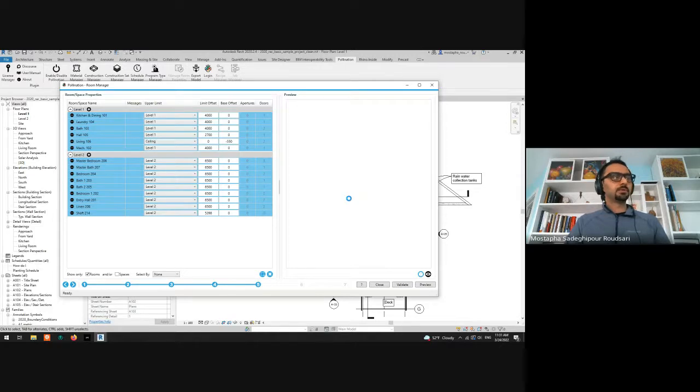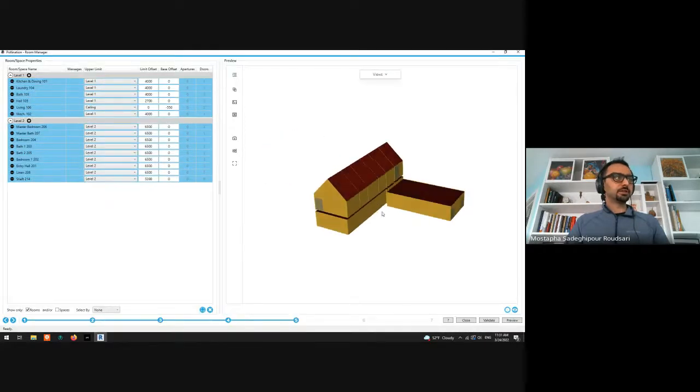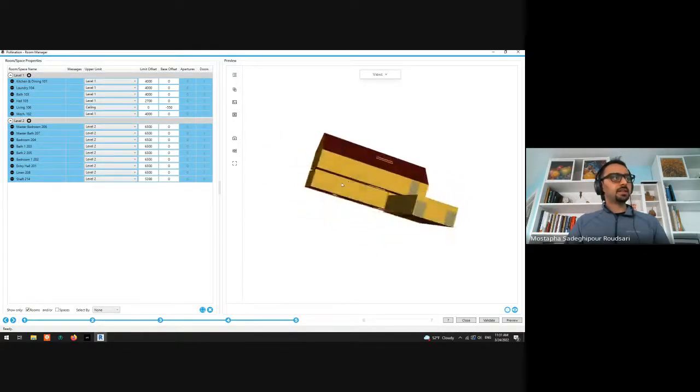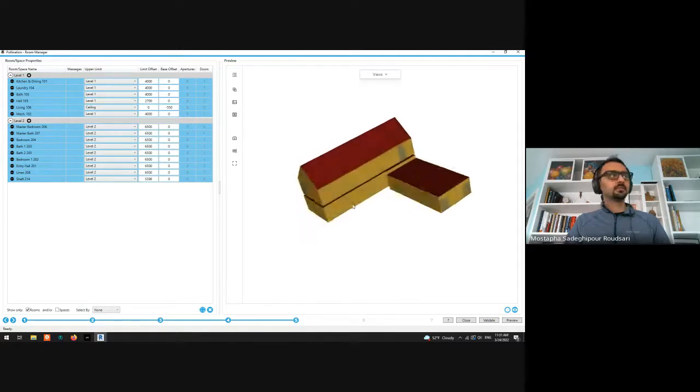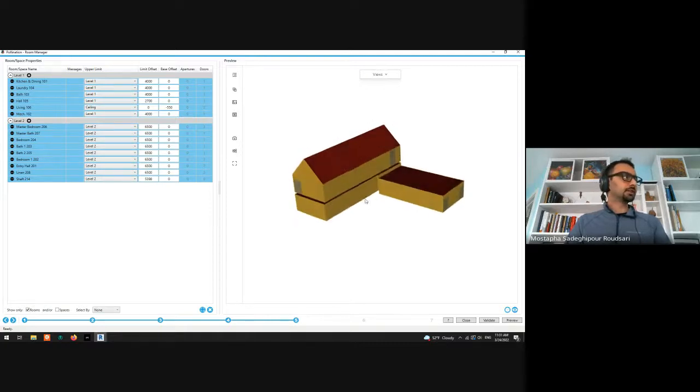And you should be able to see the 3D model of your analytical model inside Revit without doing any export. So what happened is, because I didn't select any apertures, as you can see, it has no windows, but it exported all the geometries correctly. Does it make sense so far? If you have any questions that I have to answer, let me know in the middle.